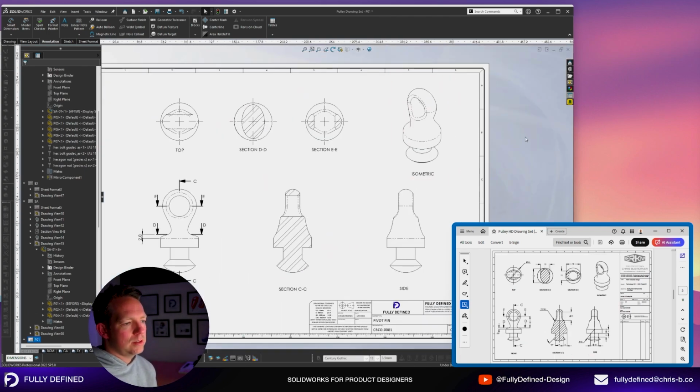Now, the easiest way to dimension your parts is generally to think back to the way you modeled it and what information you created it from in the first place, because those are going to be some of the key dimensions that you'll need. In this example, there's a lot of dimensions around that bottom section with the revolve, some to do with the hole, the dome on the top, and the dimension of those planes. Using the dimensions that were set as your design intent are generally good for adding to your drawings. But not every dimension needs to be added.